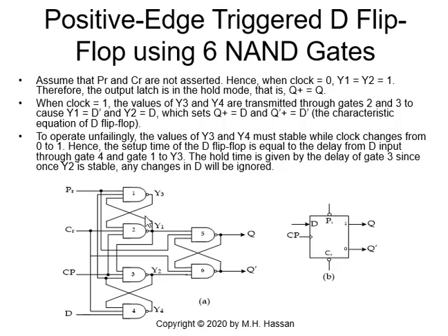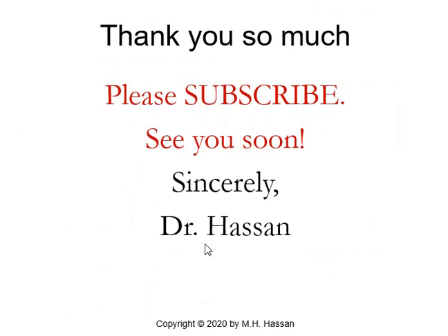So this is a simple description of this 6 NAND gate D-type flip-flop, and it is positive edge triggered. It is an excellent invention, an excellent replacement for the master-slave design of a normal flip-flop based on the JK flip-flop. Now, this is actually the last slide.